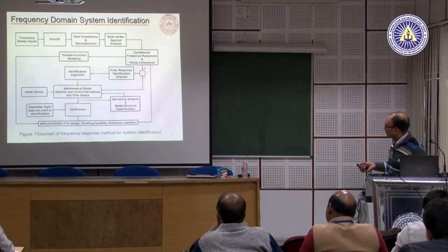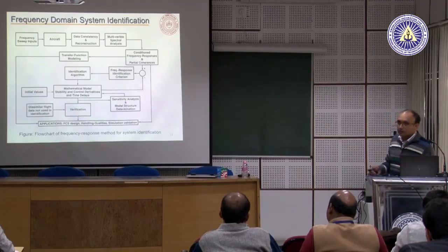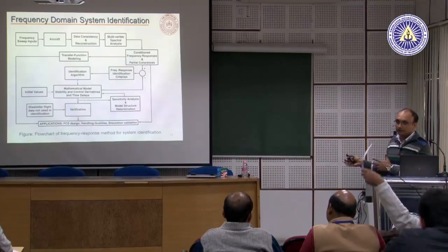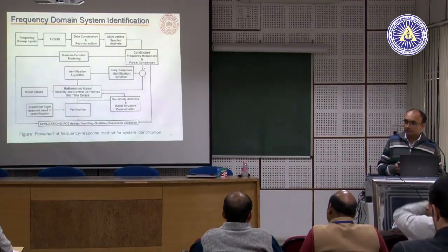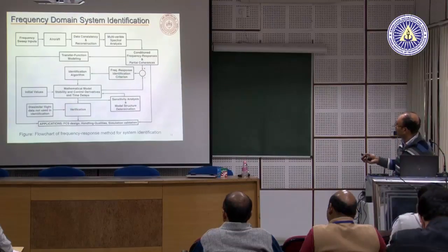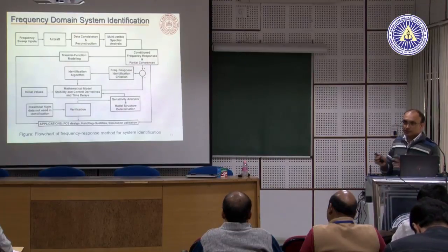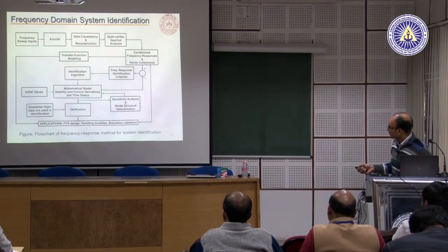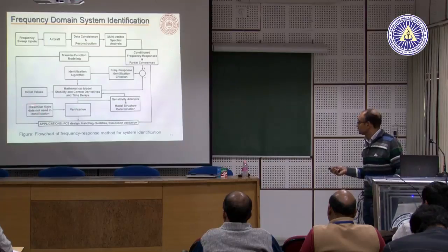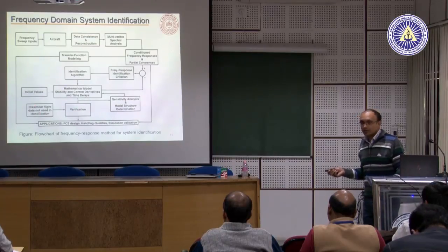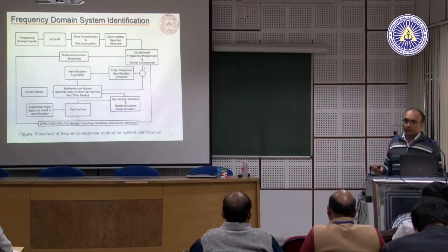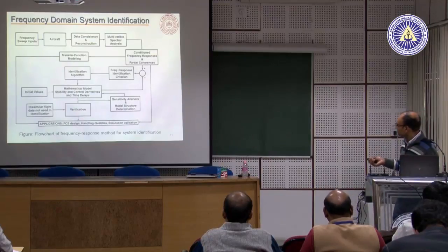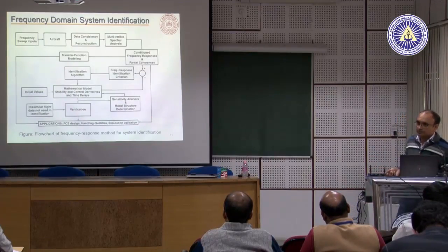Now once the model is identified, okay, when you perform so many flights, you will use most of the data for your identification, but you will also keep some extra flight test data which will not be used in the identification of the model. These extra flight cases are going to then be used for verification. So you can see here, the similar flight data which was not used for identification would be used for verification. Okay. And once you get reasonable match and you are satisfied with the correlation between the flight test and the identified model, then you can use it for all kinds of purposes.